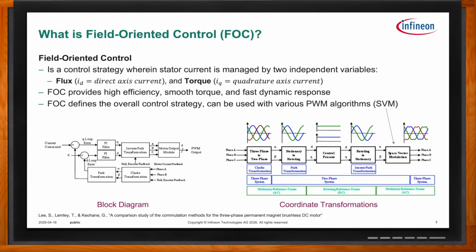And then you have to go from rotating frame to stationary frame and so on. And then finally, there's the modulation, the PWM modulator at the end. And here again, you can use different types of modulation. Most commonly is what's called space vector modulation, SVM, but there can also be others, third harmonic injection. There are certain two-phase approaches to simplify and reduce power and whatnot.